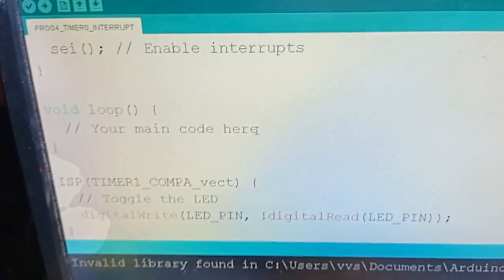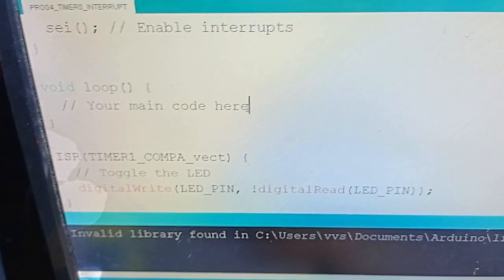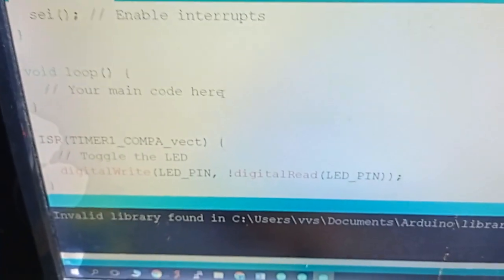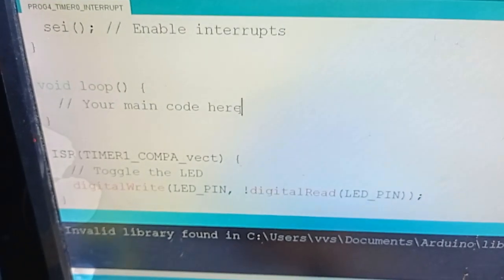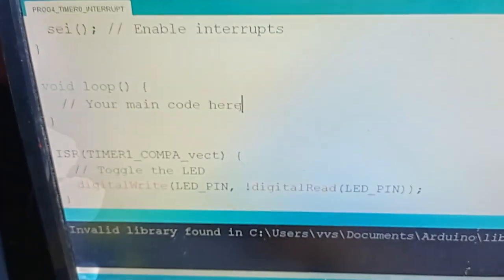So you are basically saving the power of the processor. Generally the power of the processor gets wasted during the functions which we call delays. That is the basic level of writing the code. But if you want to save the processor's valuable power, you can use interrupts rather than using delay functions.